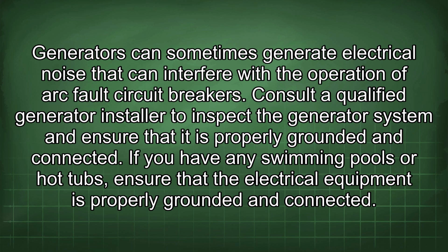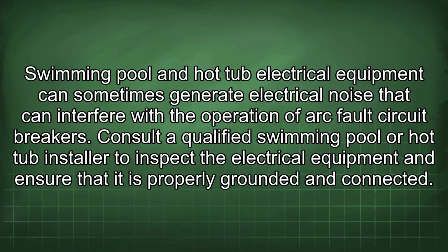If you have any swimming pools or hot tubs, ensure that the electrical equipment is properly grounded and connected. Swimming pool and hot tub electrical equipment can sometimes generate electrical noise that can interfere with the operation of arc fault circuit breakers. Consult a qualified swimming pool or hot tub installer to inspect the electrical equipment and ensure that it is properly grounded and connected.